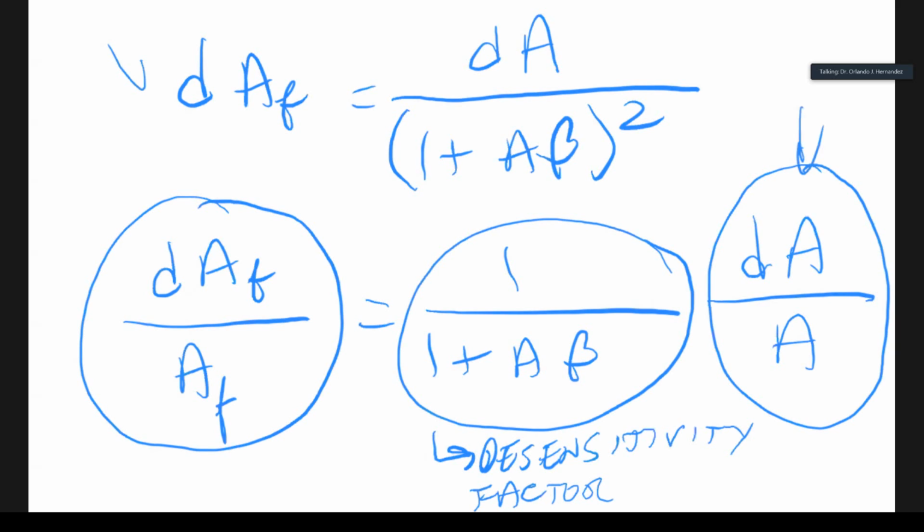But because of the feedback introduced, specifically the negative feedback inherent in this expression with the help of the feedback network, that change here is reflected much less in the actual change of my system, which is the closed loop gain, which is what I care about. So this is a very useful result and shows the usefulness of negative feedback.